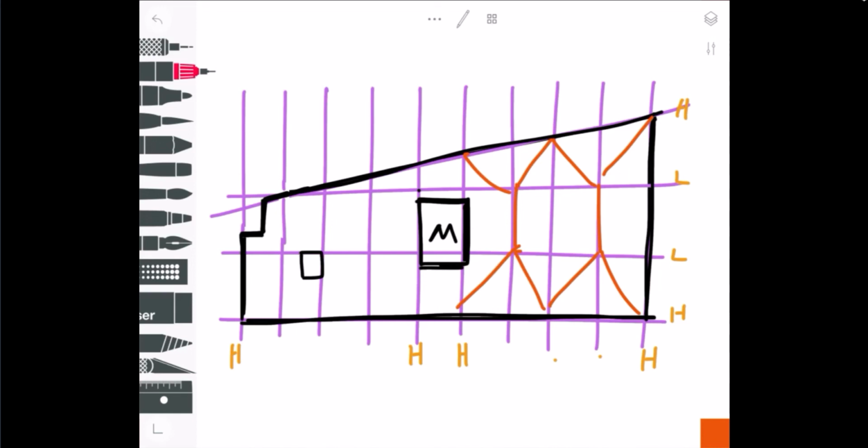So this one here is going to be, oh, this is an interesting one right here. It depends where the column would be in this thing, but the beam is probably running, let's just say we have a beam running this way, and then we have a beam running this way. Either the column would be here or there, and the beam would either cantilever over the column or the column would be at the exterior wall. But either way, it still works out there.